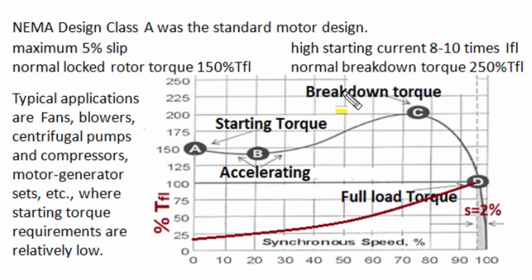But since these motors have a small amount of rotor leakage reactance, they produce a considerable breakdown torque, and their maximum torque capacity is 250% of full load torque value. They also have very good running operation due to small rotor resistance, and their maximum torque will occur only at a slip value of 5%, and full load conditions will occur at a slip of only 2%. So due to the small operating slip at load conditions, they have small rotor copper losses and very good high efficiencies.